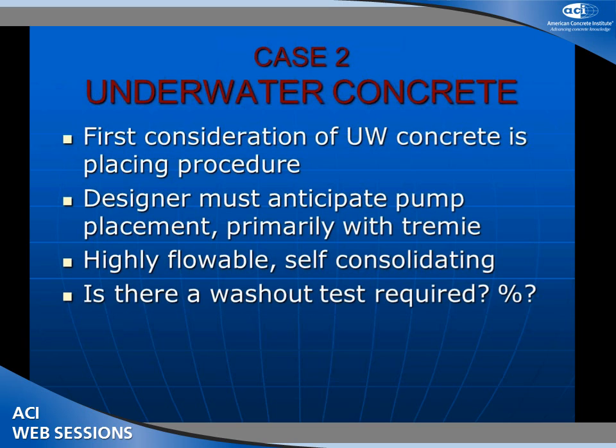He turned the bull float 90 degrees to the handle and had catwalks across the top of the pour, and he used that with a tape on it. We didn't think about tide changes, but that was his elevation control on the water. It was about a 20-foot deep pour. So pump placements typically are going to be used for this.